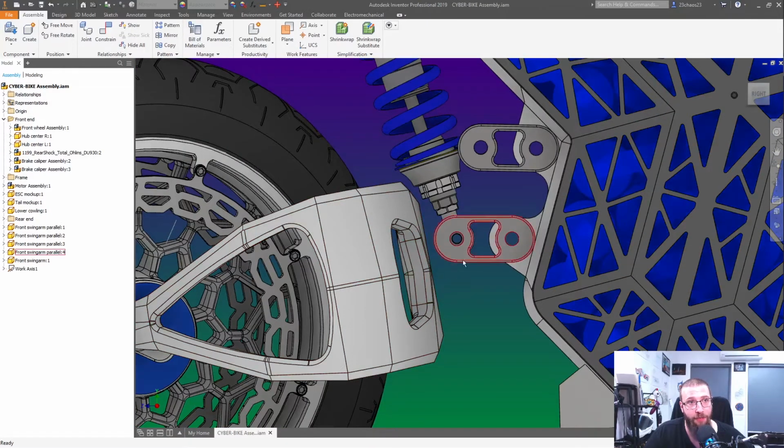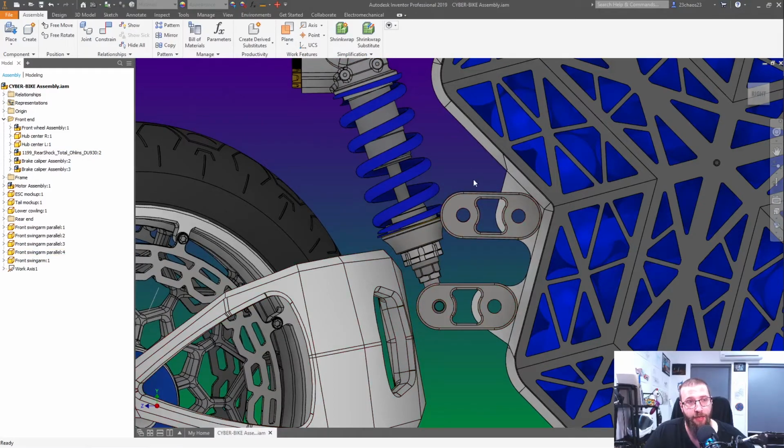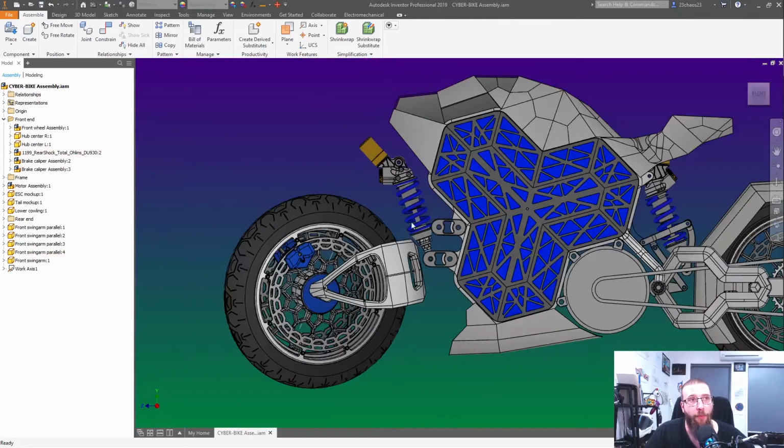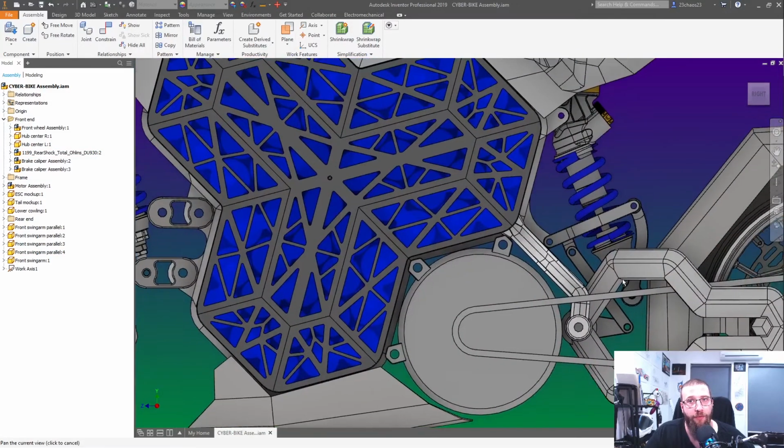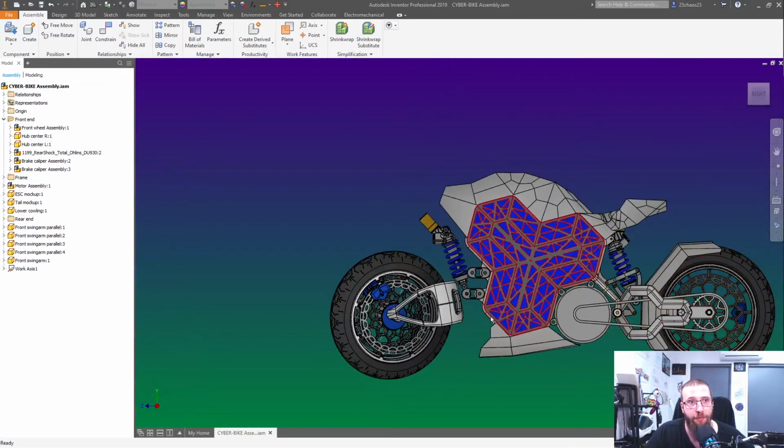I'm just going to come in off the back of this and replace the extension that connects it to the parallelogram and to the swing arm. We don't think we're going to bother with a force multiplier like we did on the front, because it is on a parallelogram, so it's going to have a different kind of movement, so we want slightly softer interaction with the shock. We don't want to be using a force multiplier or a force divider. We want exactly what it's got.